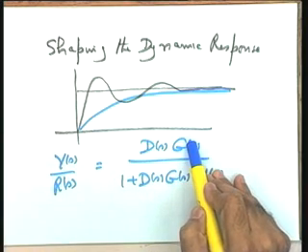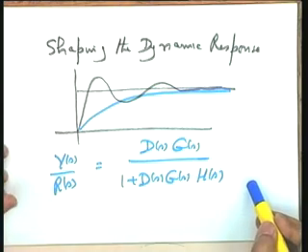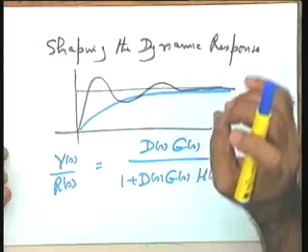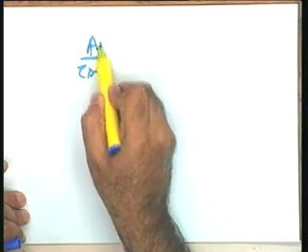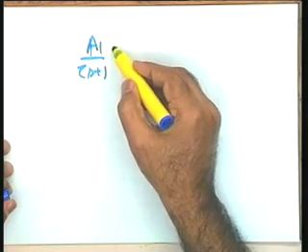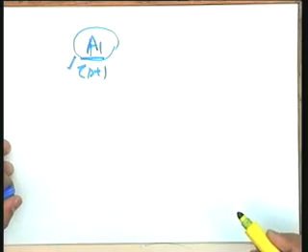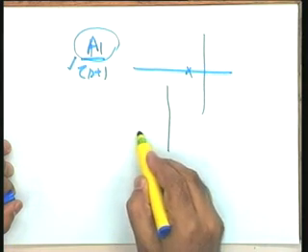You can appreciate this particular point. As far as the zeros are concerned, when you take the partial fraction expansion for example, the zeros will affect only the residues, magnitude, and those residues will affect the magnitude of the response. The nature of the response will be guided by the pole. Okay. For example, if the pole is a first order factor, 1 over tau s plus 1 into a, in the numerator I have a1, the zeros only affect the magnitude of a1 and the poles affect this tau. And you know that if my tau is here, the response may look like this.